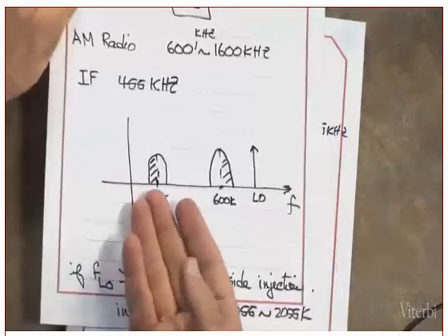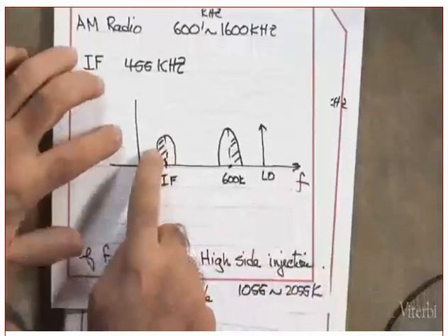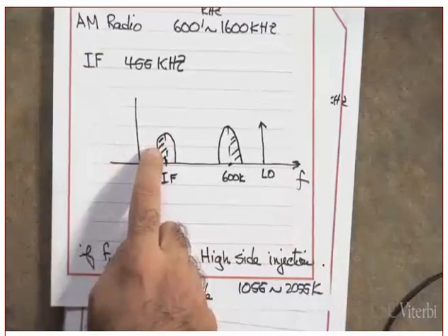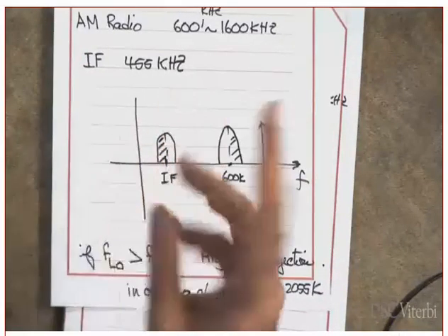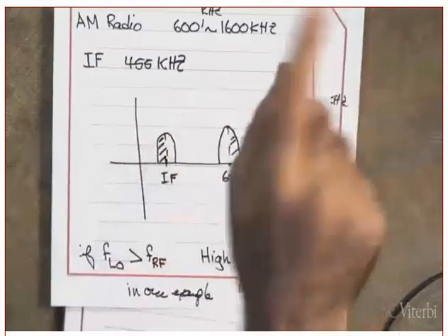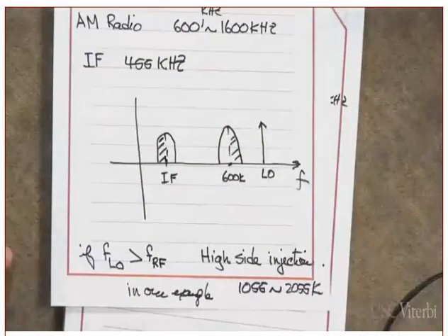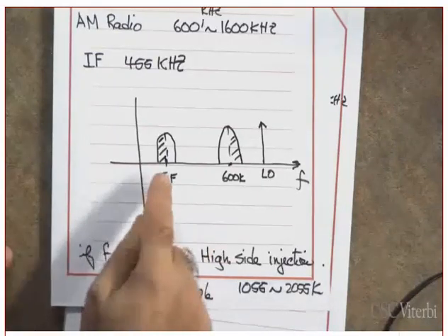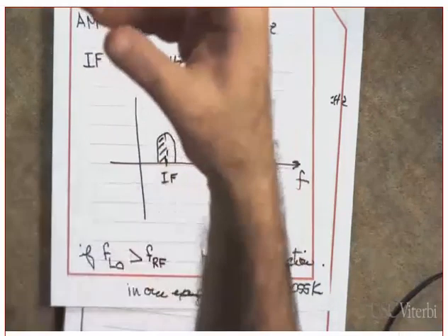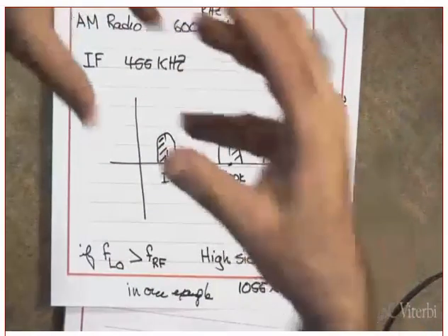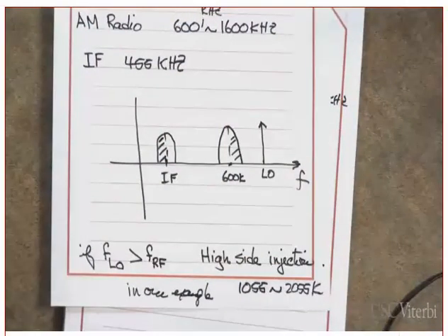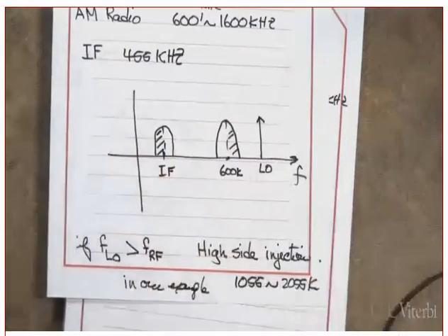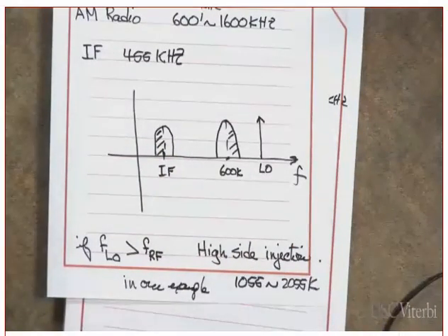Now you might say, okay, so inverted. In some situations, these might not be identical. In some other situation, some other modulation, if you invert the spectrum, the modulating signal might get also inverted. The 0 becomes a 1, and the 1 becomes a 0. But that might not be a major problem if you do have multiple mixing in the RF chain. Because, for example, if you do have two mixers in the RF chain, if this one inverted, the other one will invert it again. Did you get my point or not?